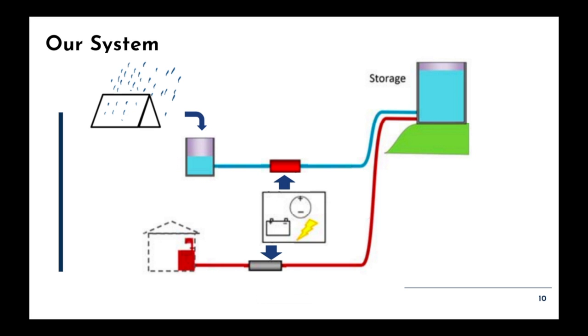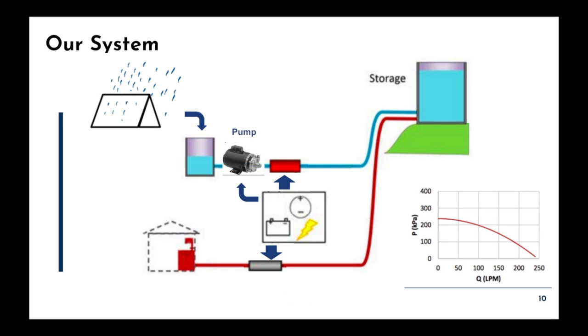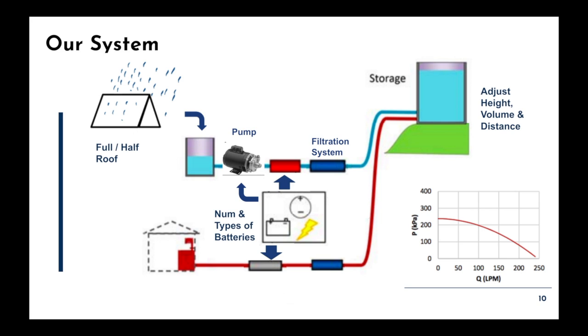We decided to use Pump B, which uses 120 volts of AC power, and referring to the plot on screen, we believe it will have the optimal pressure versus flow rate relationship for a long-term water system out of the pump options given. We decided to use a 200, 5, and 1 micron filters and the UV system to filter. The addition of the 5 and 200 micron filter is cheap and worth the added maintenance filter costs. We decided to use 2 12-volt lead-acid batteries for our design, where the alternative would be to only use one, which greatly lowered satisfaction and reliability ratings.